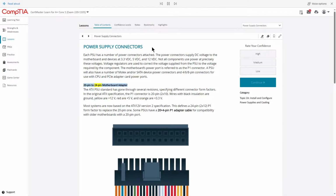20 pin to 24 pin motherboard adapter. The ATX PSU standard has gone through several revisions, specifying different connector form factors. In the original ATX specification, the P1 connector is 20 pin, 2x10. Wires with black insulation are ground, yellow are plus 12V, red are plus 5V, and orange are plus 3.3V.